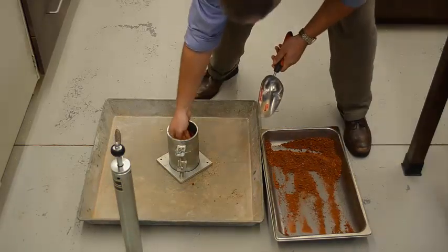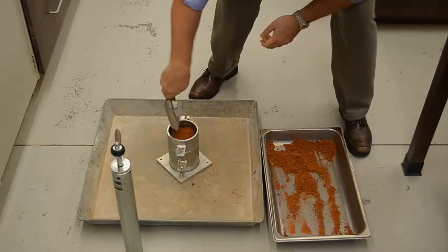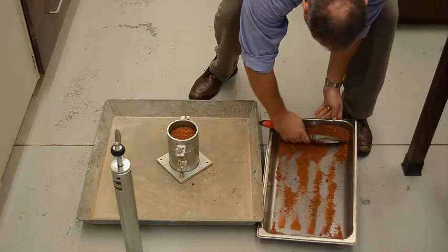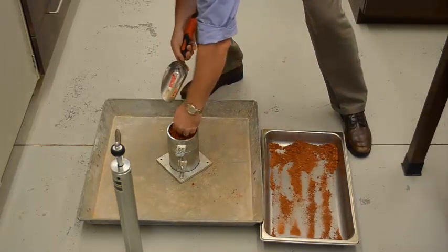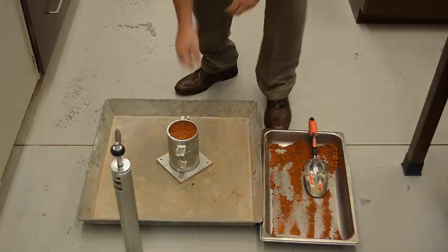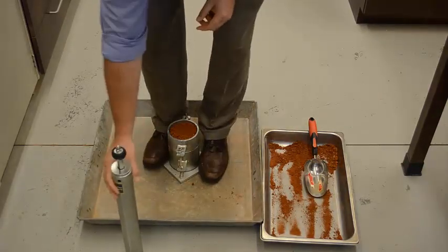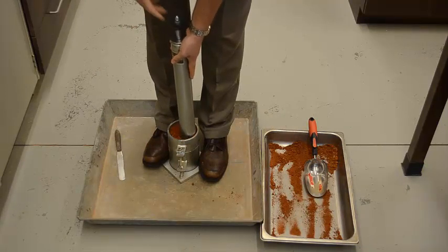So those were 2 half scoops, so we're going to need a little bit more than that, obviously, because this will compact down, and we want to make sure that this last layer, once compacted, is above the top of the mold, or above the bottom of the extension collar that's there. Okay, so you usually pack it down with your fingers a little bit to be about 3/4 of an inch to an inch below the top of the extension collar.